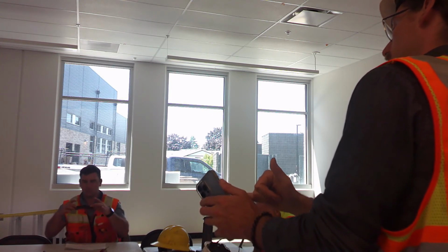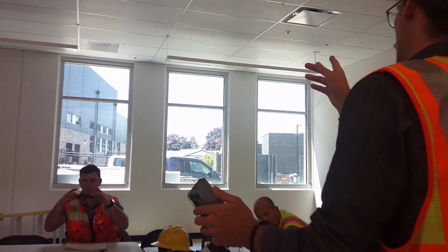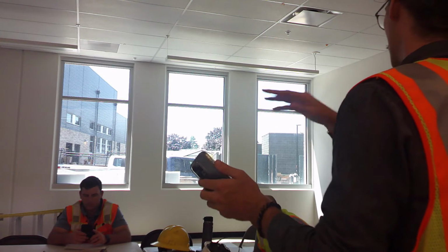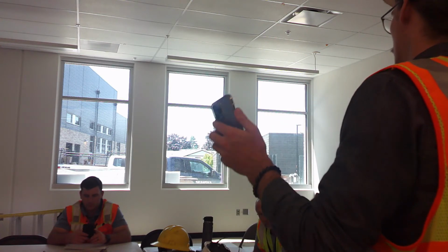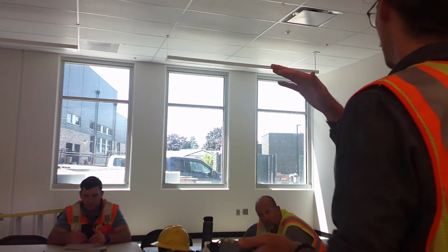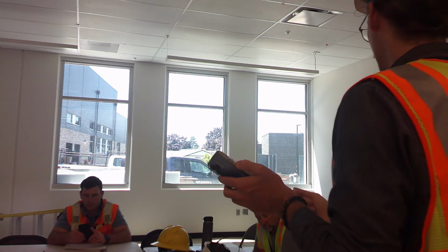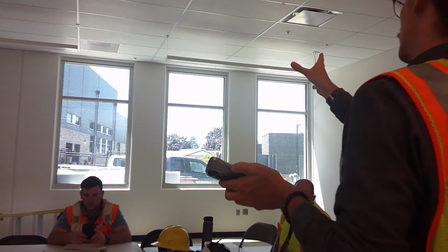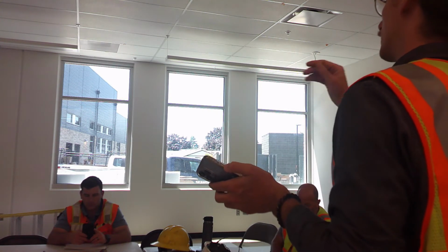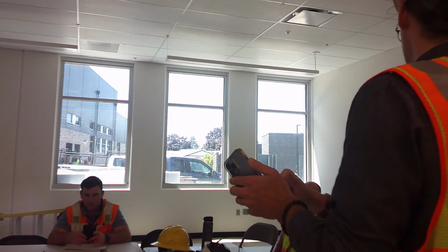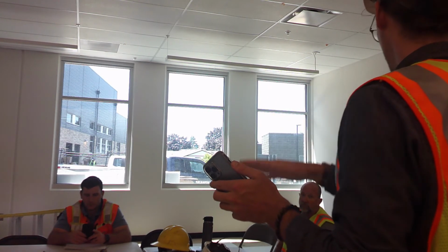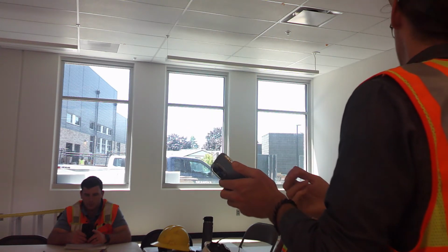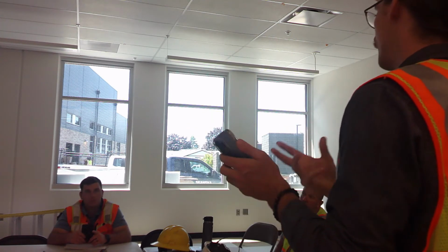This zone 1 is programmed at 120 at the sensor. So what that means is once the sensor hits 120, the lights are going to be at 1%. If the sensor was at 60, they'd be at 50%. Make sense? So if for some reason you're seeing that we want these lights to be brighter, you want to raise up that sensor value so it takes more light for them to dim down, and vice versa. If you want it to dim more, lower the sensor value, and then they'll dim with less light at the sensor.